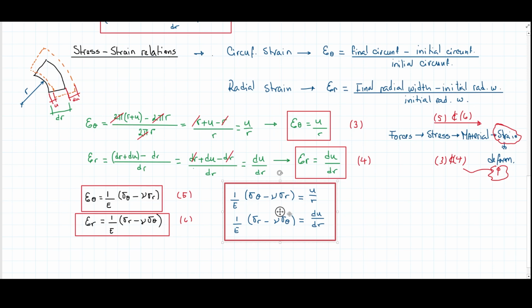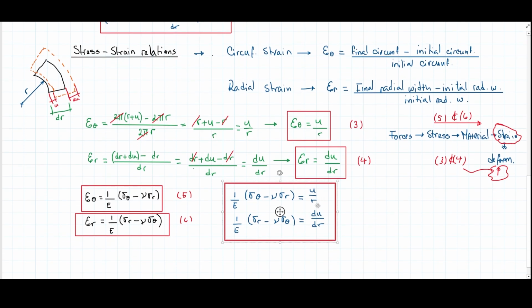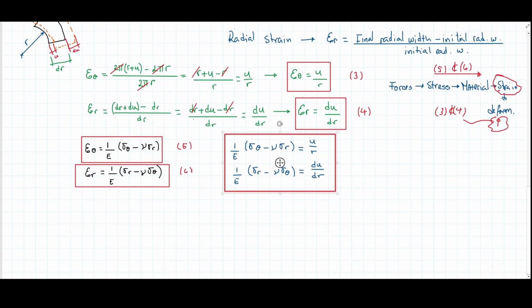Because I'm having again the sigma theta stress, circumferential stress, and radial stress that I need to solve equation number 2, which is the equation coming from the equilibrium of forces inward and outward in the radial direction. But still now I'm having this u and r, and delta u as certain unknowns that I need to see what's going to happen with. So let's see, where should we start? Let's start with the first one. Yeah, it looks better.